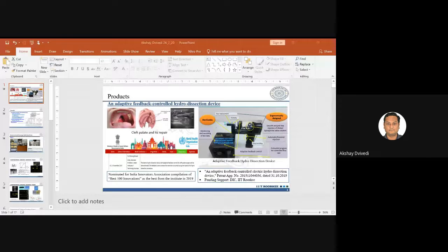Now, since you are continuously increasing the voltage, there will be a case where this film will break down. In fact, it will be breaking its dielectric strength. And from that point, certain sparks will be emitted, and you can see those sparks here in my figure. Now, when these sparks come out, they create a certain temperature, and with that temperature the material reaches a point where it melts.